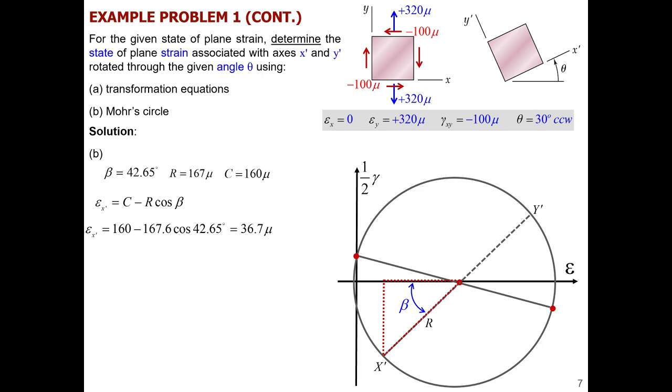Alright, so now the next step would be to calculate gamma here. Right, so this is basically this coordinate from 0 to here. And that again can be done fully on consideration of this triangle. So we know r and we know beta. One thing to remember here is that we are not getting gamma, but this coordinate is actually half gamma. Right? So that's this half gamma in the new coordinate x prime y prime will be r multiplied by sine beta. So then that factor 2 I can transpose to the right, and so then our gamma actually is 2r sine beta. Now I can substitute.